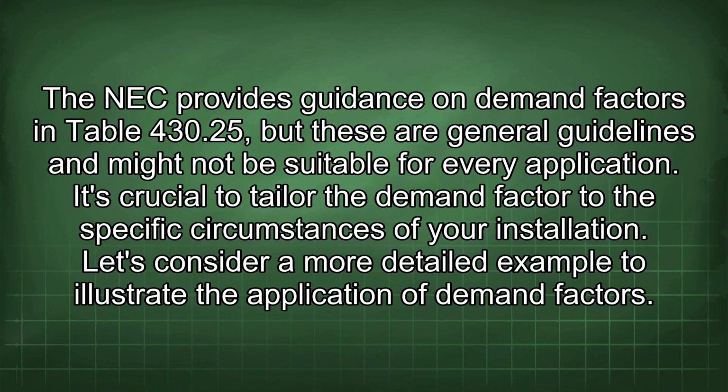The NEC provides guidance on demand factors in Table 430.25, but these are general guidelines and might not be suitable for every application. It's crucial to tailor the demand factor to the specific circumstances of your installation.